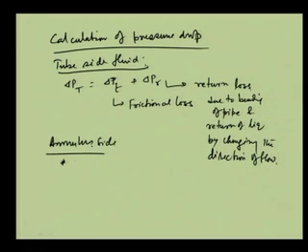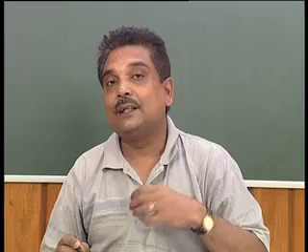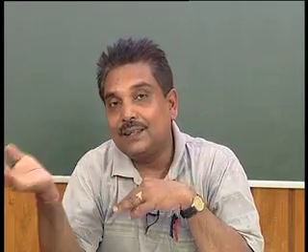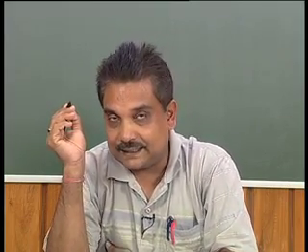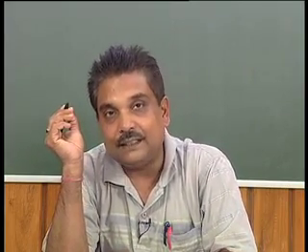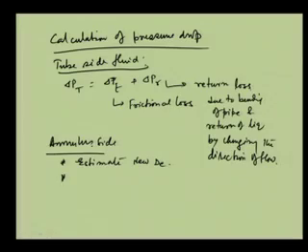Again, that D equivalent has to be taken, because during the pressure drop the frictional loss can happen for the fluid touching the inner surface of the outer pipe, and therefore that frictional loss has to be taken care of, and that D will be different. So, the effective or equivalent diameter will be different.